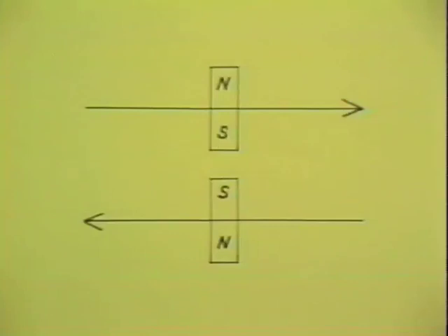The signal from the horizontal oscillator is a series of pulses. Due to the inductive nature of the coils, these will produce currents in the coils which rise and fall linearly with time. The currents produce magnetic fields around the coils and make the coils behave like magnets. As the current changes direction, the magnets reverse polarity. The magnetic field deflects the electron beam in the tube, so the coil is oriented around the neck of the tube to a position where it will deflect the beam horizontally. As it changes polarity, it deflects the beam the other way.